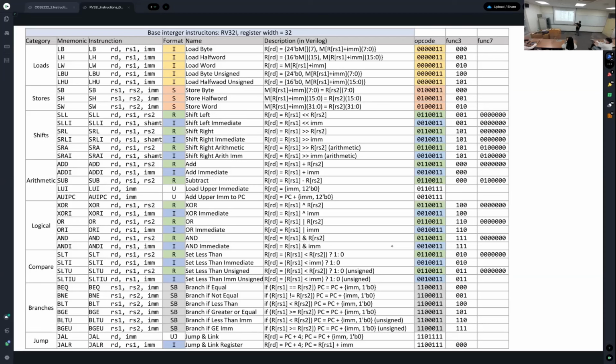learned about the arithmetic instructions. As you can see, arithmetic instructions have add instructions. So we learned about the add. This is the different form, as you can see. And then we learned about the sub instruction here. So actually, this is the RISC-V integer instruction, and this type of instruction does not have multiply or divide instructions. So you can find the logical instructions here, and then also you can find the R format here.